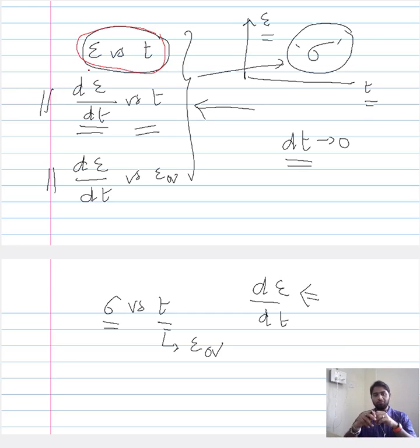So from that point of view, when you present your creep behavior in the conventional way involving strain versus time, the information it delivers is more appropriate for the application. And that is the reason why this is termed the conventional way. This has become the conventional way and people prefer it.